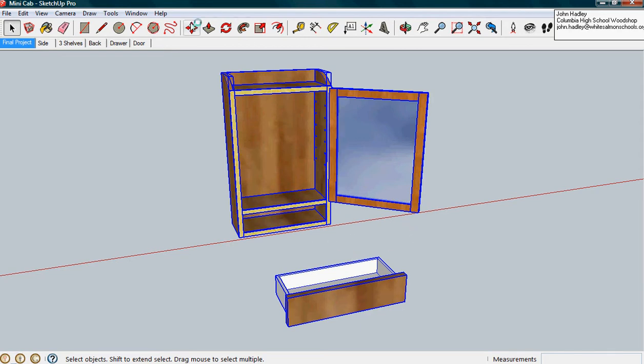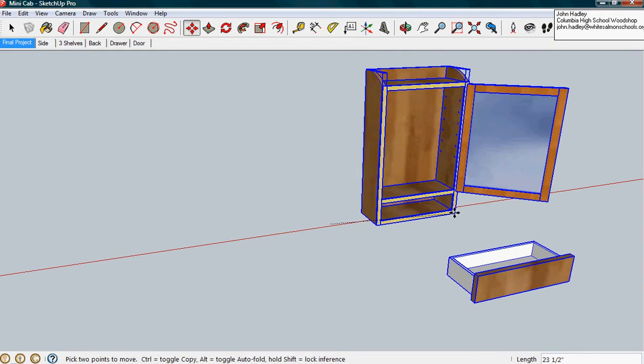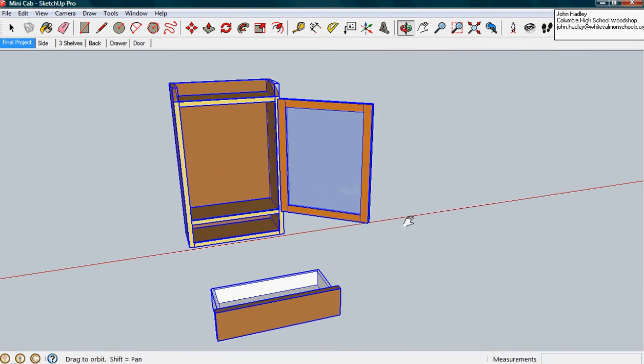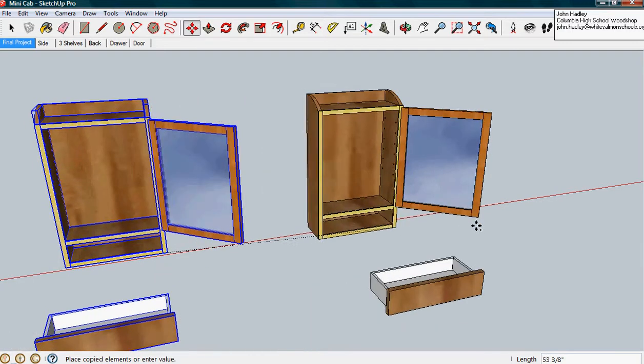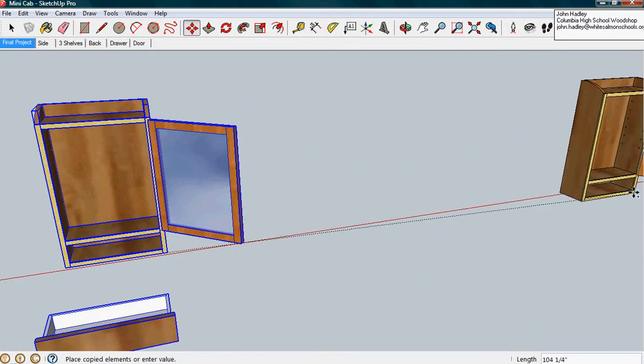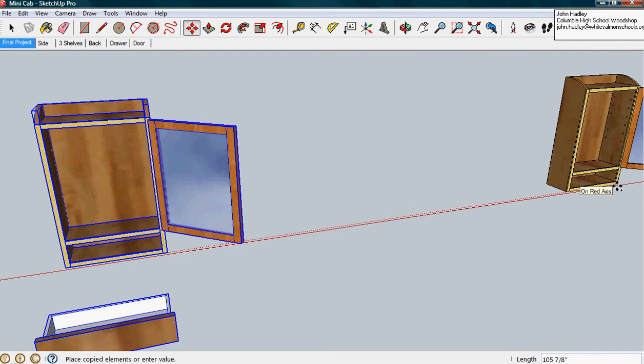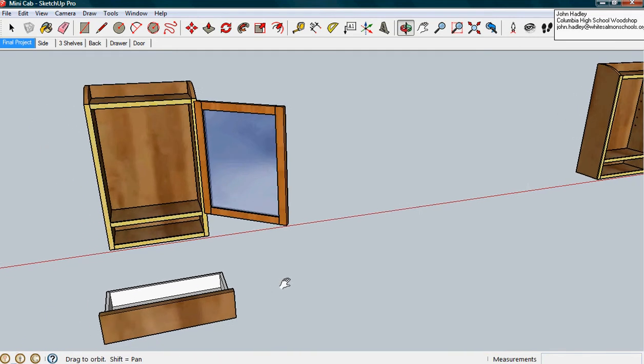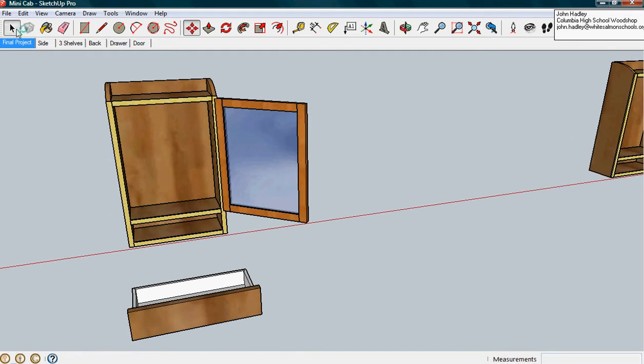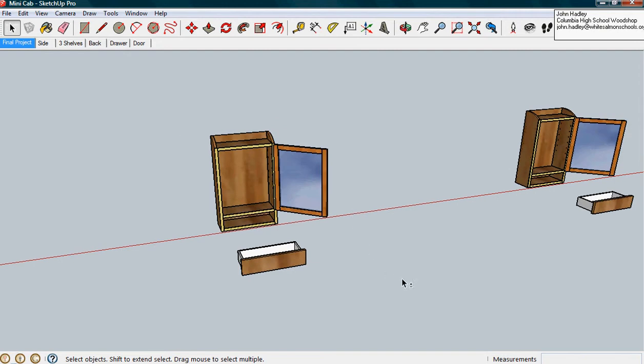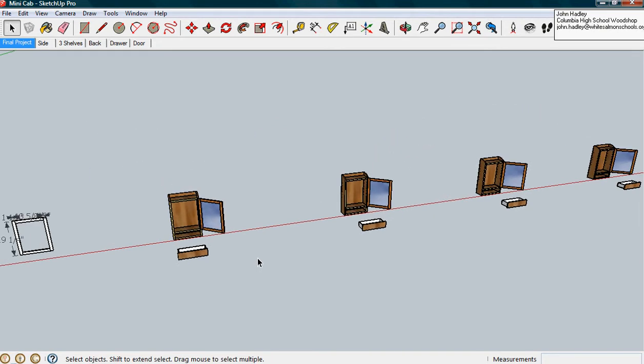You just take that whole thing, select it all, and then you bring it down the way, put the original back, move it down a ways, just far enough to be kind of out of sight, and then do Shift 8, which is times, about times 4, enter. The more detailed pieces that you have, the more times you're going to need to iterate it or make it multiply itself. So when we do this, we can see that there's more of these out in the side direction,